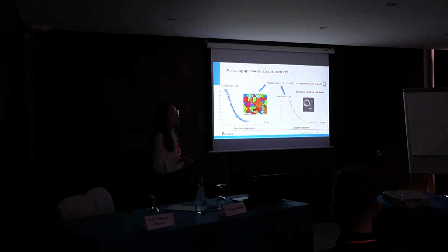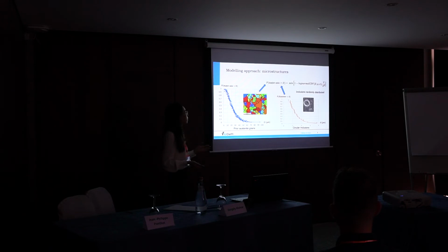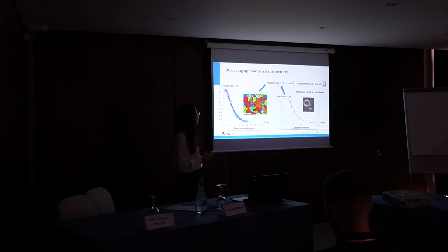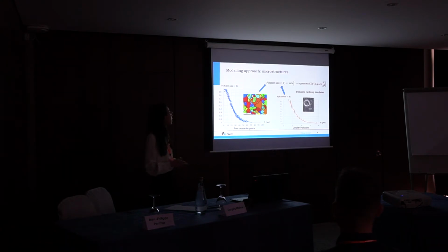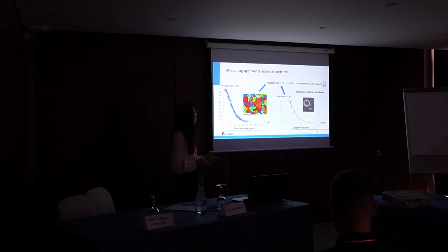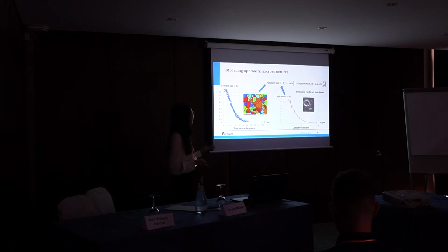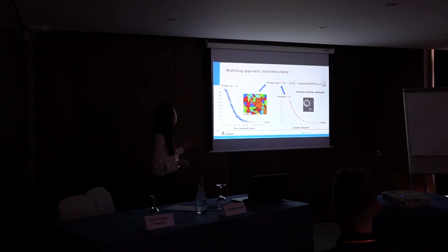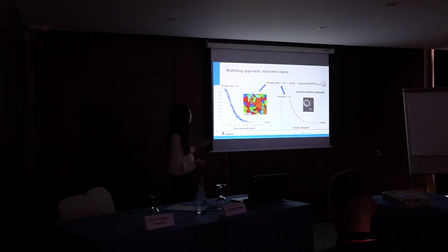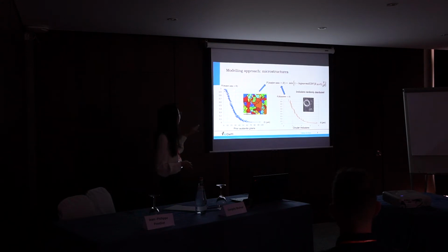There are several inputs for the model, and here I want to emphasize the input of microstructures. We are using two types of information for the microstructure: one is the prior austenite grain size, and the other is the inclusion size. For the prior austenite grain size, we measure them from an EBSD scan. We reconstruct the prior austenite grains and measure the major axis of the grains. Here the points are the measurements from the scan, and the solid line is the fit to a combined function of a log-normal function and a power-law function.